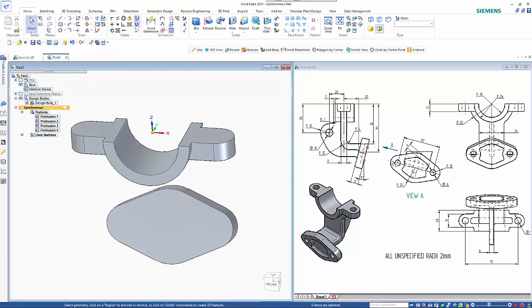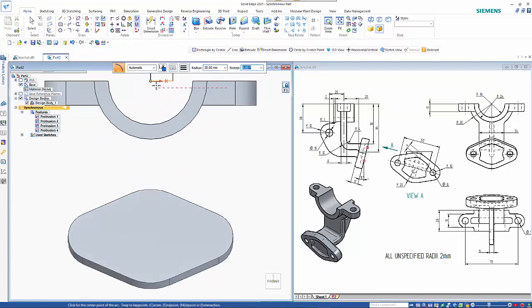So from here I'm looking at creating this piece down here, so it's a 30 rad and 34 width, dropping down to 51 plus the 8. I'm going to bring it down to the bottom edge, so that'll be 61. So again, start with the arc by center, lock the plane, 30 mil rad, Control H takes me through to the sketch view,